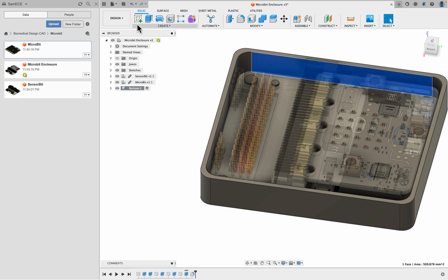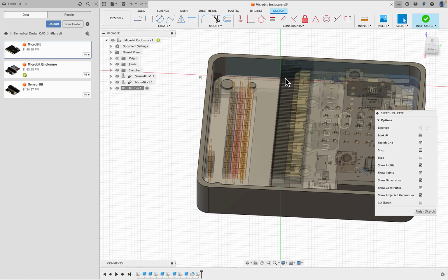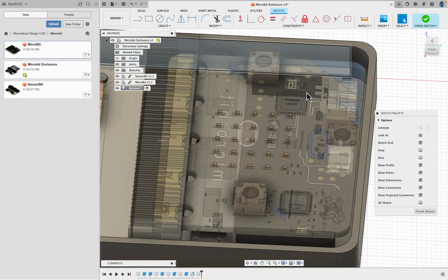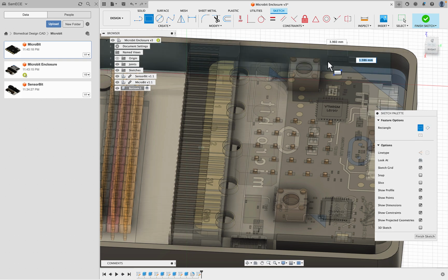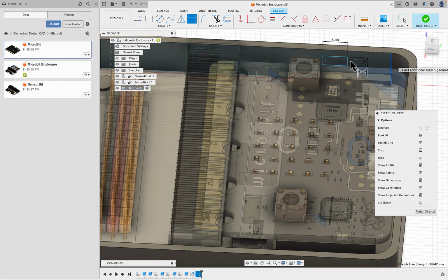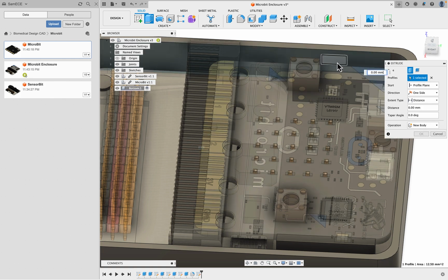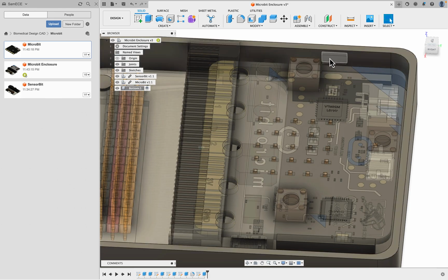So I'll do a cutout on this side. Just rotate it a bit so we can notice it. So in this case, I'll just draw a rectangle and say this should be here, and let's create one about 2.5mm in height and 5mm in length. And I'll just hit D and position it 9mm from this edge and 1.5mm below the top edge. So I'll hit finish and do an extrusion of this little part by, let's say, -0.75. So this just creates a little gap in the wall.